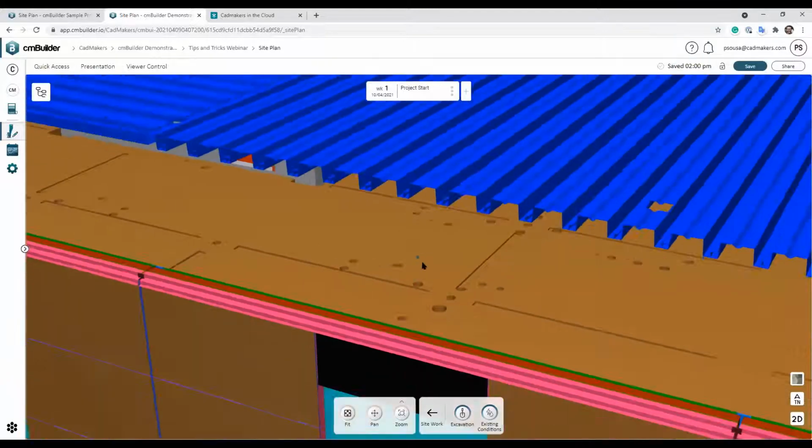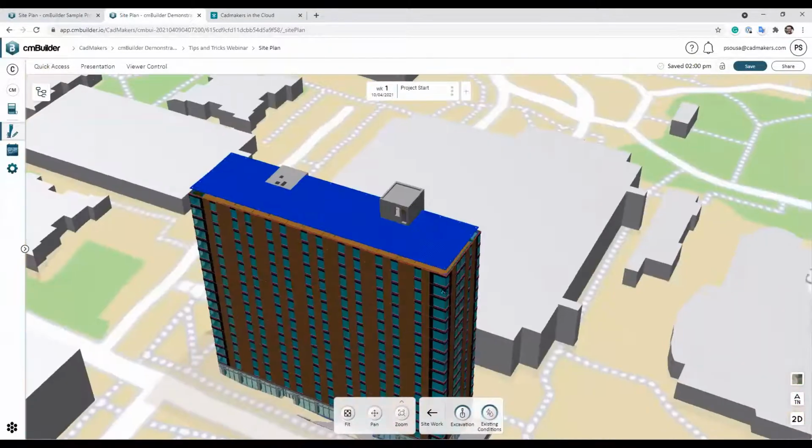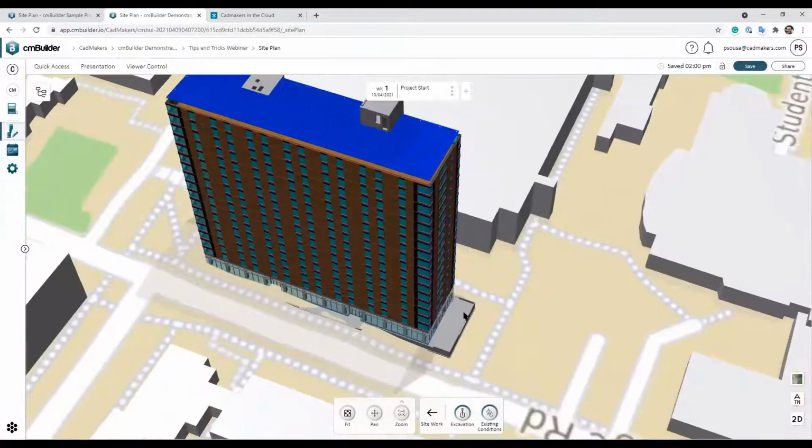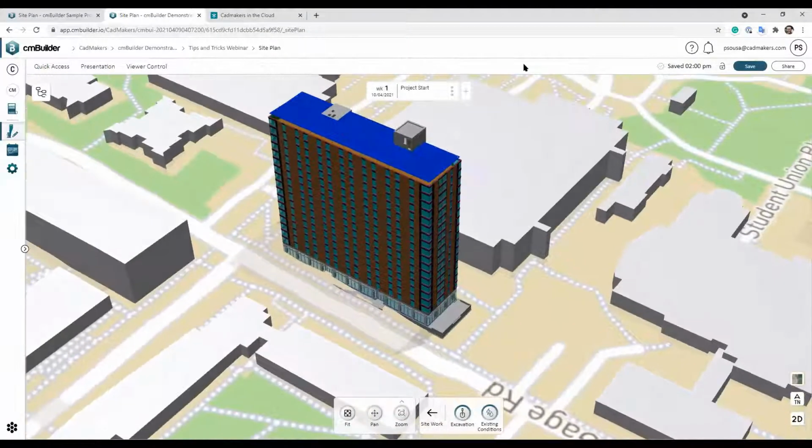You could also overlay a 2D drawing, right? And then on top of the slab, let's say for that MEP riser, and then basically line up the model with the drawing. That's another way to visual ref. Exactly. Thanks a lot, Javi.